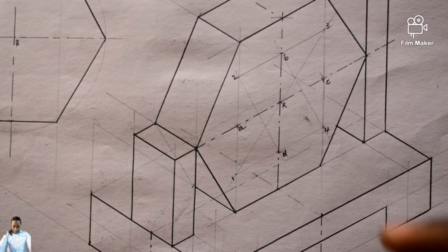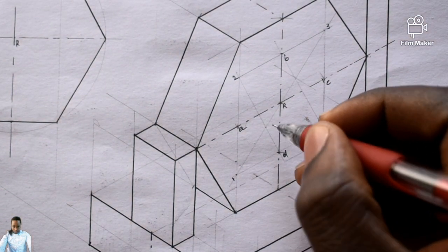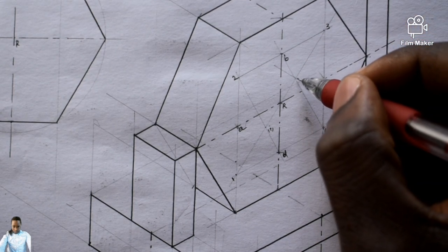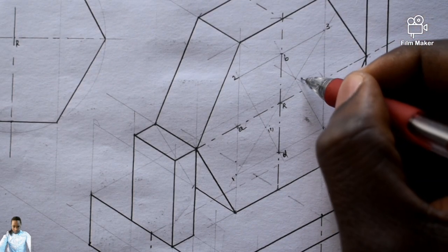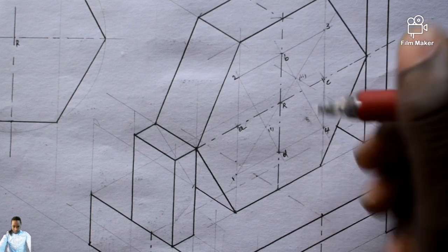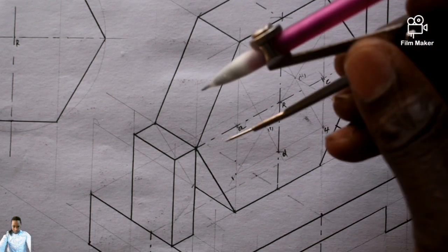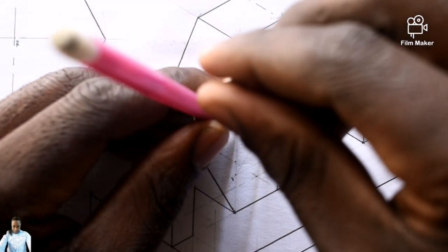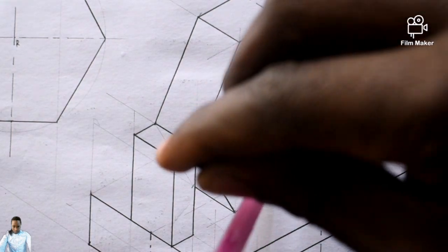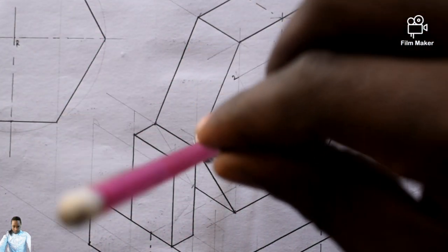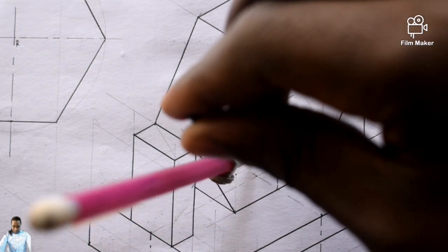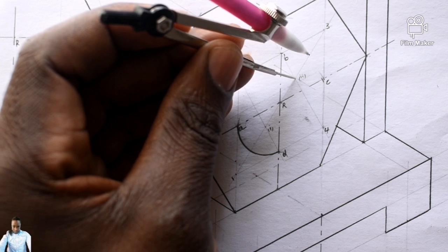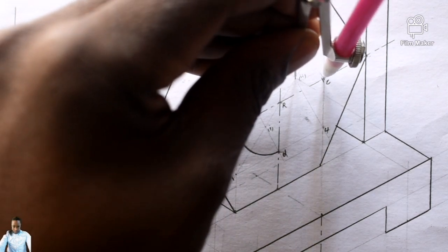There you go. So at that point, I'm having my Roman figure 1. At this point, I'm having my Roman figure 2. So now I'm going to place my compass at Roman figure 1, further extended to point A. So I get a line that's going to be dark from A to D. And now place my drawing compass at Roman figure 2, further extend to point C and B.